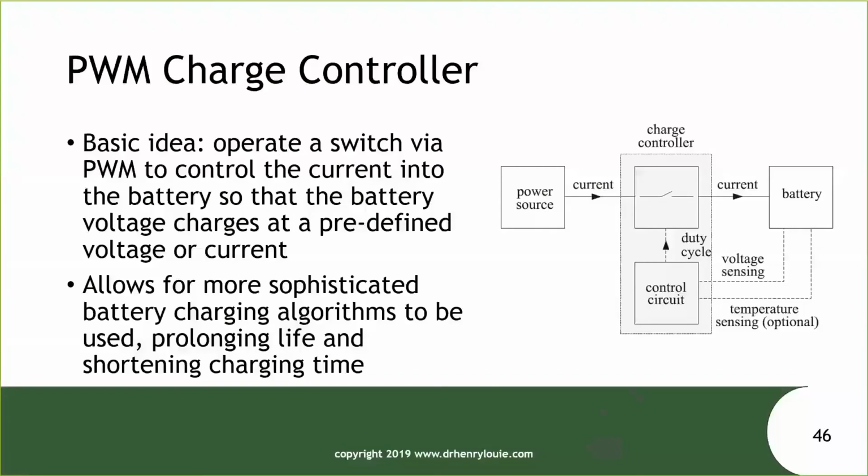Okay, so just briefly then about charge controllers. So what we do with the charge controller is we're trying to prolong the lifespan of the battery, and we do that often by sensing the battery voltage and operating a series like chopper switch to regulate the current into the battery.